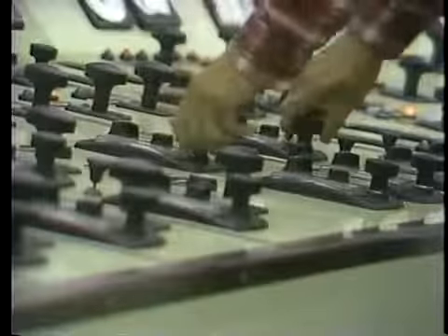There is another piece of equipment in the plant that sometimes is prone to fires. That's the air preheater. On rare occasions, changes in normal operating conditions, an incomplete boiler purge, or even dead spots in the flue gas flow path through the air preheaters may allow combustibles to accumulate inside. In the event that one of these situations occurs, a fire may result. An operator can generally increase airflow through a burning air preheater and blow the fire out.